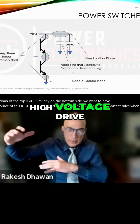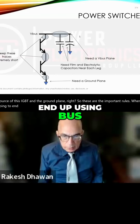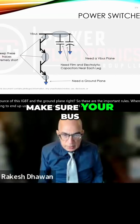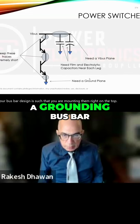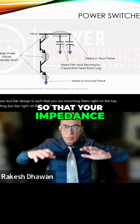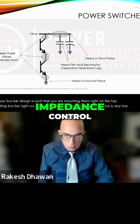When you have a high voltage drive, you are going to end up using bus bars connecting different IGBTs. So you want to make sure your bus bar design is such that you are mounting them right on the top, and then you have a grounding bus bar right on the top of these IGBTs so that your impedance is very low. So it's called impedance control, right?